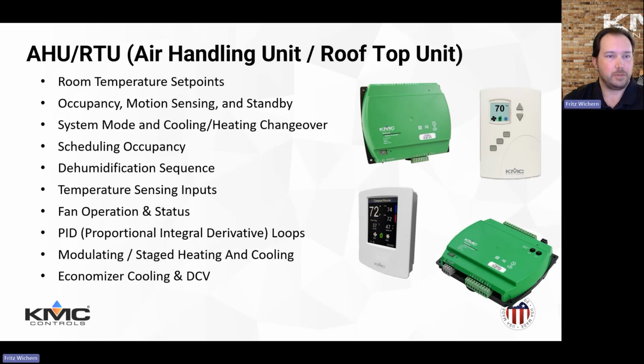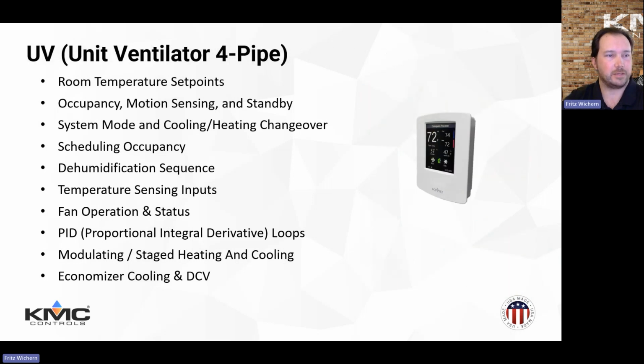Next up, with our unit ventilator, sorry, I was thinking with our FlexStat option, we have a unit ventilator profile, which is the same setup as we have in the others. And actually, I don't think there's much difference between the unit ventilator as the others. So it's really just taking a look to see what fits your inputs and outputs the best and what controller fits it the best, whether you want to use the FlexStat on the wall or use one of the other controllers up at the equipment and use a net sensor in the space.